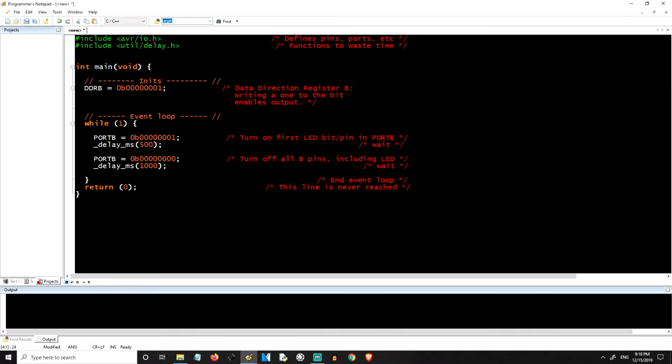You can also define things up here. So say we want to include some sort of predetermined integer, the amount of time we want something to delay. We just say, what do you call this these days? Hashtag or hash, #, whatever. And we're going to say define. So we're defining a specific variable, and let's call it blink speed or blink delay. Let's call it blink delay.